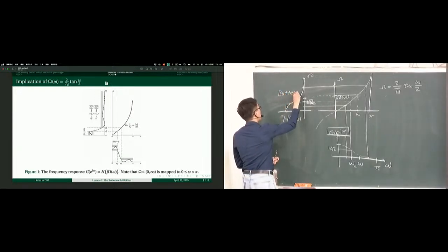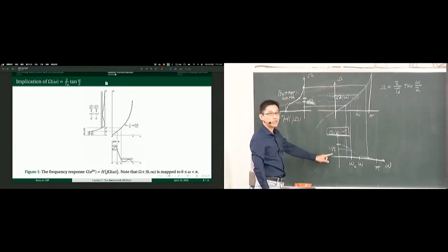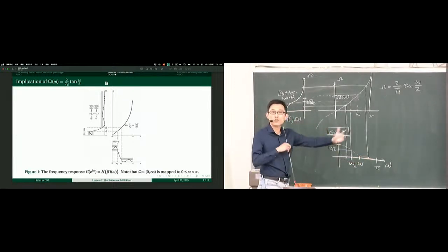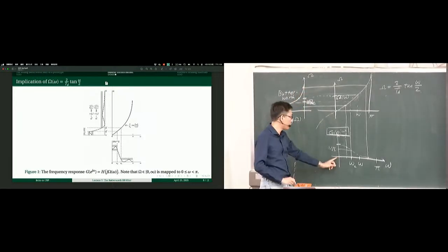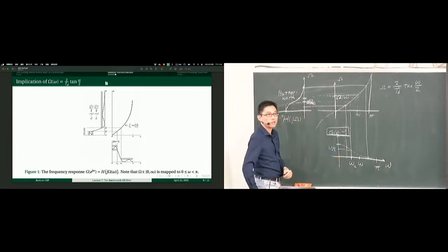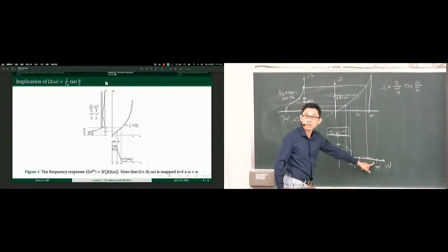So in this sense, by just plotting more and more points, you'll figure out that indeed you begin with an analog prototype and you end up with a digital filter design. And the general shape will be the same. The only difference is a compression of the frequency axis. Now the frequency axis originally is from DC to infinity, but now we compress it to the finite interval between 0 and pi, which is exactly what a frequency response ought to be defined over: the region between 0 frequency, DC, and pi, the Nyquist rate.